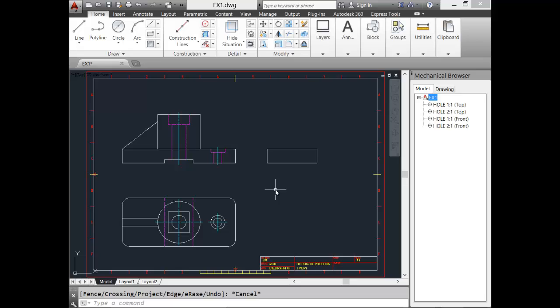Now I'll project my cylinder. If we think a little bit, we'll see that our cylinder in front view and in the side view will be the same, because it's a cylinder. At the top view we have a circle, but at the front view, when looking at it from the front or from the side, it's a cylinder with this diameter, so it won't change. So I won't draw it. Our AutoCAD here will help us to make a copy of our cylinder. So I'll copy our cylinder and my center line.